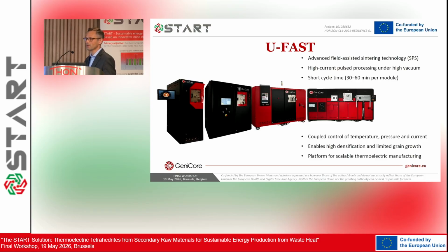The last one is the UFAST mass device, a 6 meter long device with 3 different chambers, where each chamber is dedicated to a different stage of the process, like degassing, sintering, and cooling.